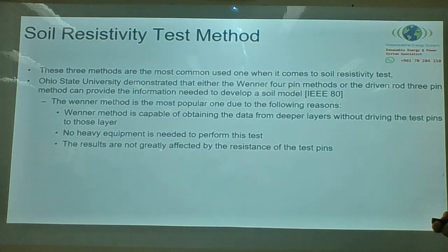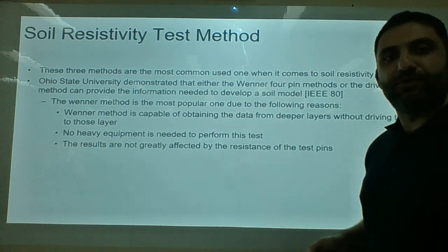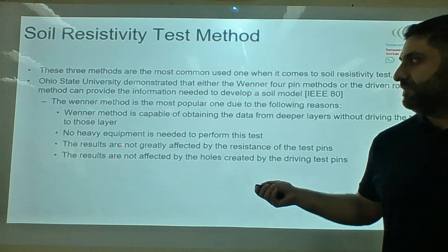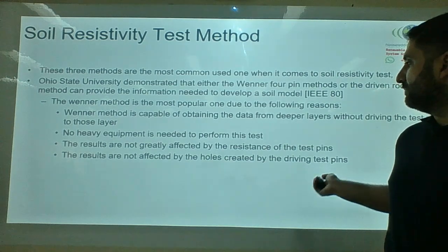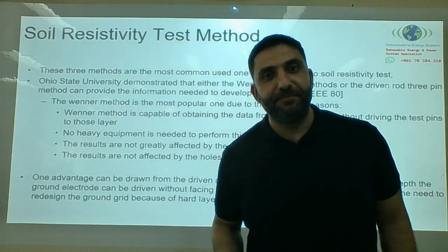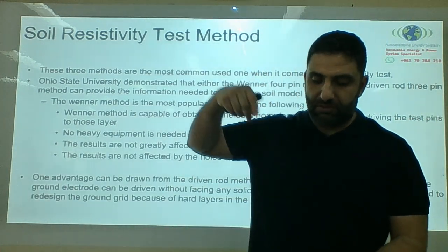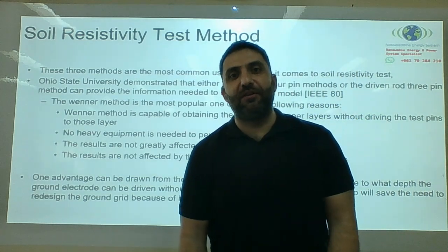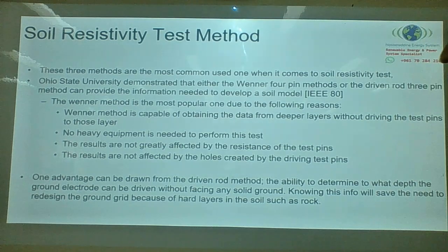The results are not greatly affected by the resistance of the test point. Not at all. The results are not affected by the hole created by the driven test point pin. Remember, when you have a driven electrode, you have a big machine driving the electrode down if you want to go down for 10 meters or 15 meters.